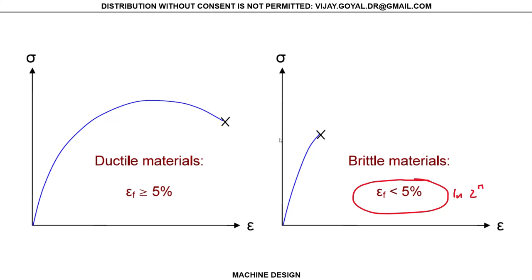You can think of the case of a chalk, right? You have a chalk and you just break it and it just broke. It doesn't have room to actually bend, to deform. Very little room for that. So in these cases, the material properties that we are highly interested in are ultimate compression, ultimate tension, and from these, ultimate compression is always going to be far greater than ultimate tension. It's going to be way bigger.